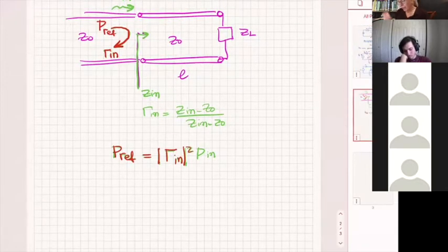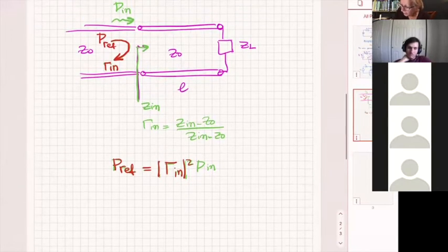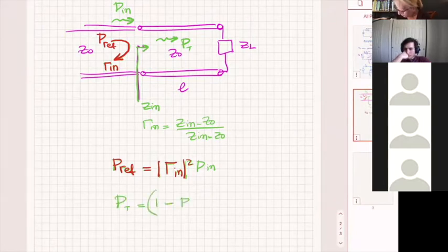I have my notes on transmission lines and everything is there, so revisit that part. If your reflected power is like that, how much is the incident? Like your colleague said, what goes down the line, and we call it transmitted power, if you want to call it that, goes into the transmission line. Then P sub T is going to be P incident minus P reflected. Let me write it from the beginning so I don't skip a step.